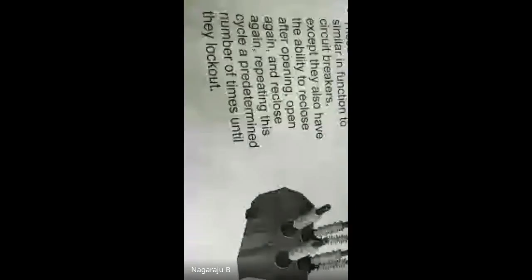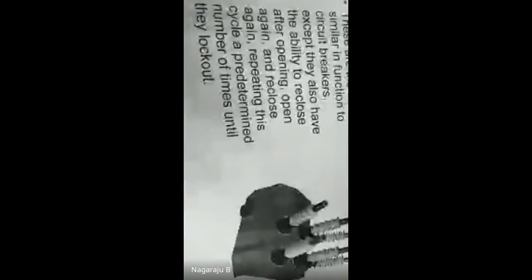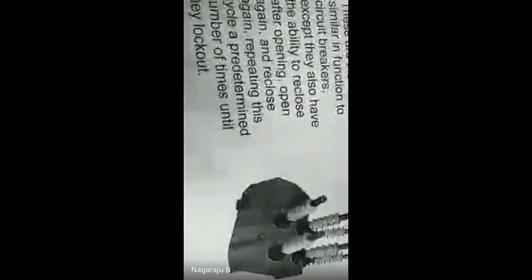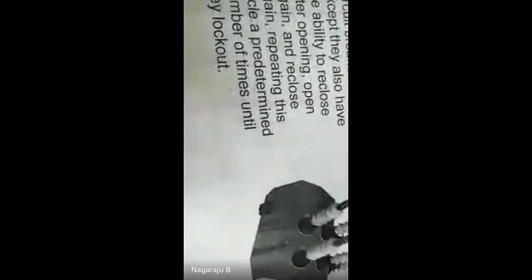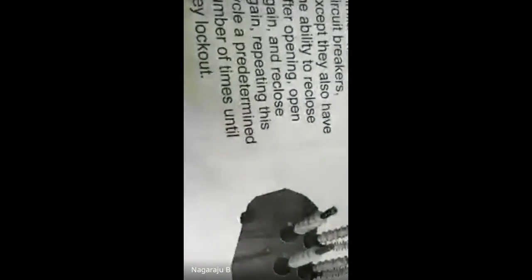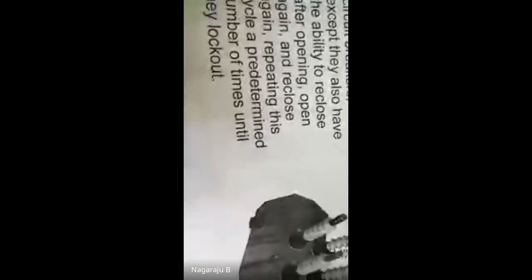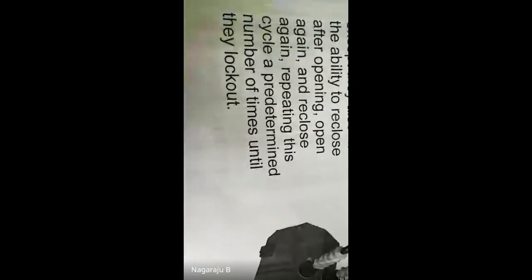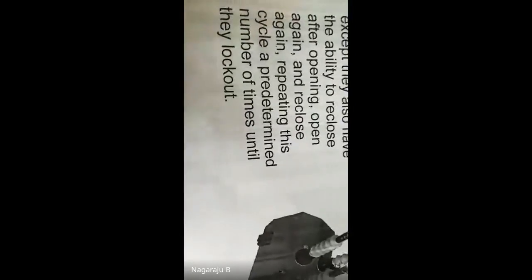Ratings range from 5 amps to 1120 amps for series coils. You need to note this. Whenever you have series coils, you need to go for the range of 5 amps to 1120 amps. For the non-series coils, I have a range which differs from the series coils.